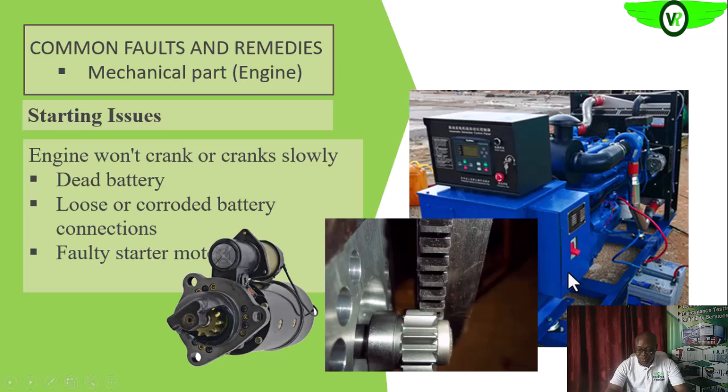Once you put on the ignition, the plunger in the solenoid will be released, and then it will push this pinion outward so that it will be able to engage the gear on the flywheel. Secondly, it has a switch here. It will make that switch contact that will send positive power to the starting motor itself. So the motor will now start turning.